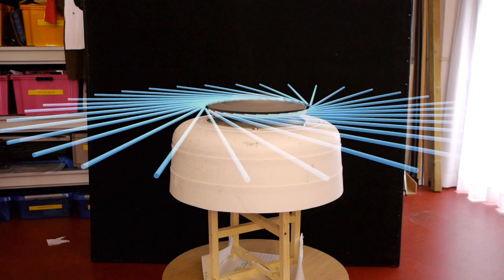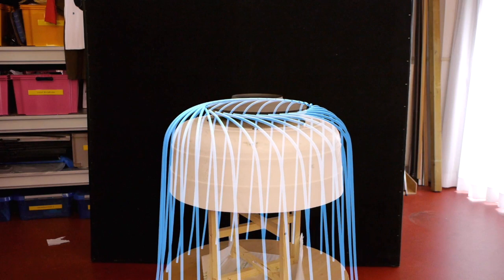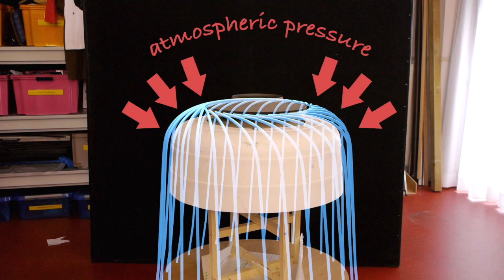So one would expect the air to flow out of the fan horizontally in all directions, but due to the Coanda effect, the air bends down to almost 90 degrees. The airflow is being pushed down by the air above, because the pressure of the air in between the flow and the curved surface is reduced by the suction of the airflow.